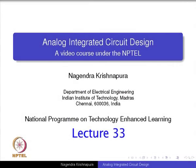Now, let us say here to the gate of MC1 I connect a voltage VG1. What will be the VDS of M1? This is VDS of M0. VDS of M1 will be VG1 minus VGS of MC1. By the way, VGS depends on the current. So, this is VGS of MC0 at a current of I0 and this is VGS of MC1 at a current of I1.